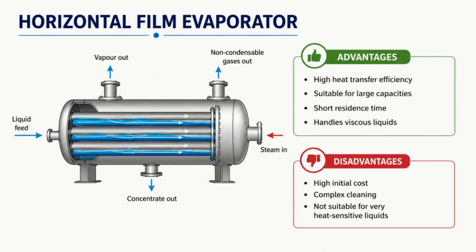So this evaporator is suitable for heat sensitive materials because heating time is very short here. So it is commonly used in the pharmaceutical and food industries. So one advantage is efficient heat transfer due to thin film formation. Another advantage is rapid evaporation with less product damage.